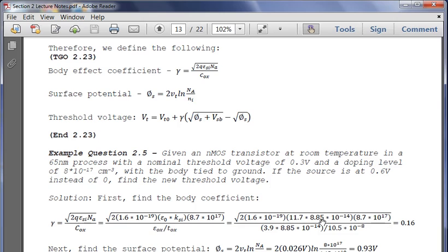We have to know the permittivity of the silicon because we have to worry about how fast the holes and electrons can travel through the space, particularly in a channel. We need to know the charge since we're calculating all the charge based on the fact that we're using the gate and transistor as a plate. And we need to consider the capacitance of the oxide itself because the capacitance has impact on both current and voltage.